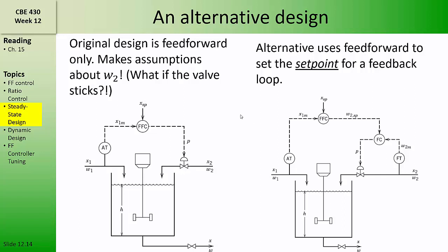The design we considered here for the feed-forward controller was based on simple steady-state analysis of the total mass balance and the component balance on the tank. In the next video, we'll consider a dynamic design, but rather than doing it in the time domain, we'll do it in the Laplace domain.